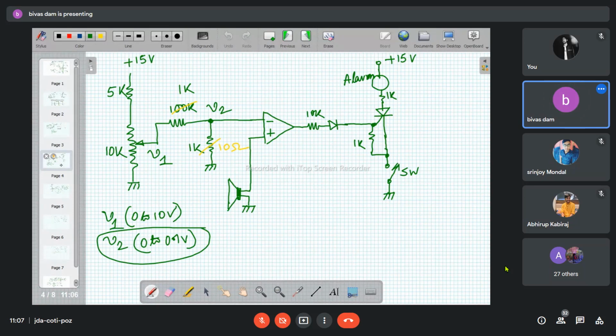Now, tell me once more about the concept of the rule of thumb. You did not read this in the reference circuit, but when you used the emitter bypass capacitor and the coupling capacitor and designed them, there was a concept that if there is a parallel combination of resistance and capacitance, we choose the capacitance value in such a manner that it is 1/10 of the resistance.